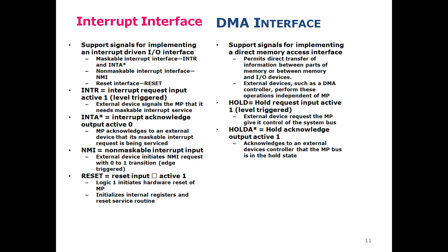so that the system bus is used for direct memory transfer, whenever the input and output device and the memory need to transfer data between them independent of the microprocessor, without passing the data through the microprocessor.